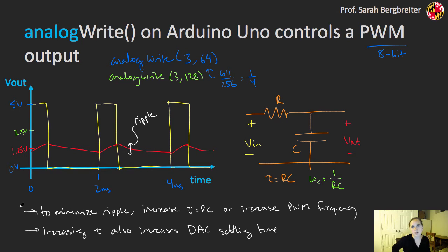So that's just one way to approximate a digital to analog converter on a microcontroller that would give you a pulse width modulated output, which almost all of them do. I need 2 external components to create my RC filter, and I can create an approximate analog voltage. I need some kind of low-pass filter on that output in order to be able to get my approximation of the analog voltage. But if I have that filter, I can get something close.